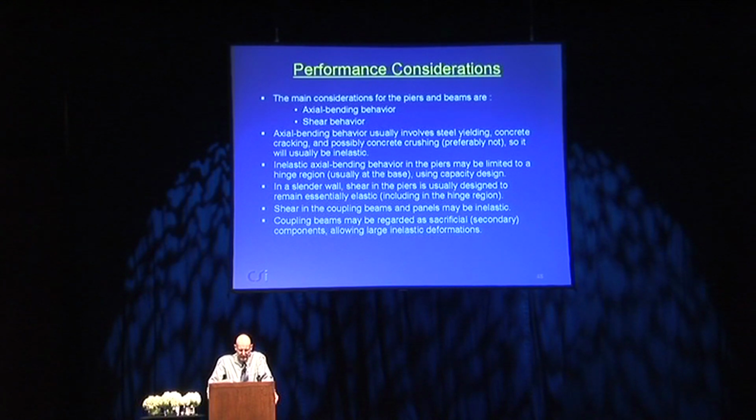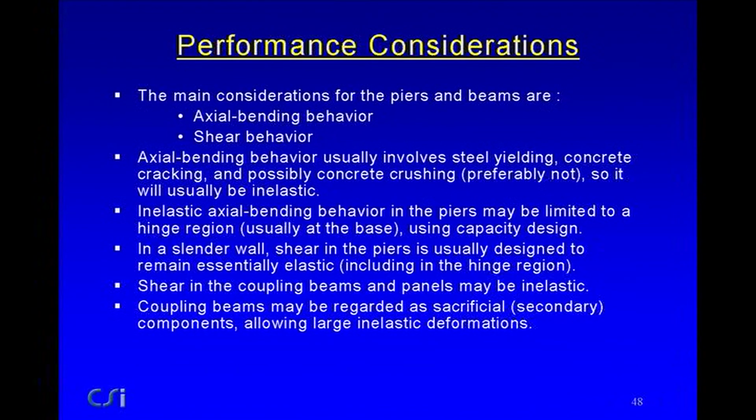Now, moving down to the second to last point, the shear in the coupling beams and panels may be inelastic. In fact, a coupling beam could be regarded as a sacrificial component which would allow larger inelastic deformations.